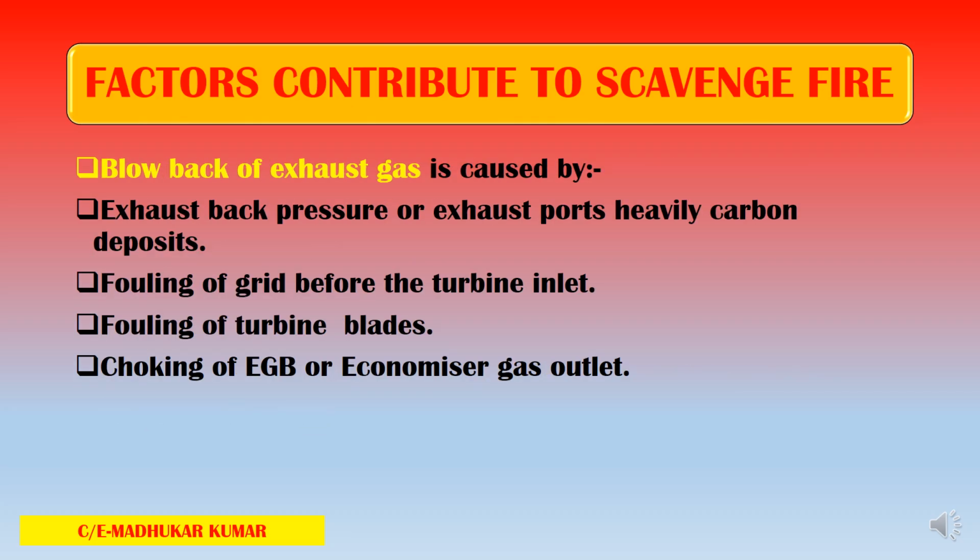This is going to cause the overheating. Now, another factor which is coming in line is the blowback of the exhaust gas. Blowback means certain back pressure. So, exhaust gas back pressure or the exhaust ports having heavy carbon deposits is going to cause the blowback of exhaust gas.